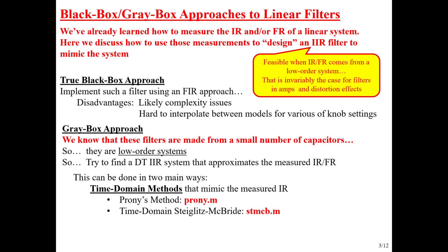So if you don't have that, you might not be able to get to it. But one is called Prony's method, and that's based upon a method developed way back in Fourier's time. Nope, he wasn't trying to come up with IIR filters, but he was solving a different problem, but the mathematics can be used to find modeling IIR filters. And then an improvement of that, which is called the time domain Steiglitz-McBride. So these are more recent researchers, maybe the 1960s, 1970s, heyday of the early DSP development.